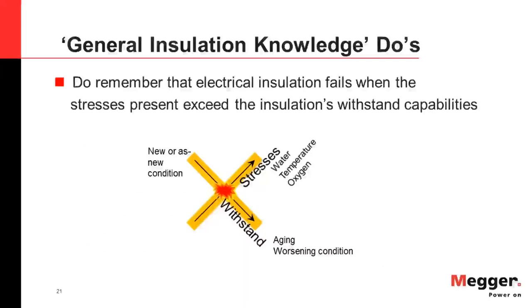And as a brand new constructed asset, it should begin its life with a very healthy withstand, sufficiently dry, ready for battle. But transformer materials such as oil, paper, and pressboard are organic materials, so it's inevitable that they will age and reach their end of life. While it's entirely possible that external sources of heat may increase during a transformer's lifetime, such as by unanticipated increases in loading on the transformer, as we discussed already, aging will also lend itself to an increase in these stressors.